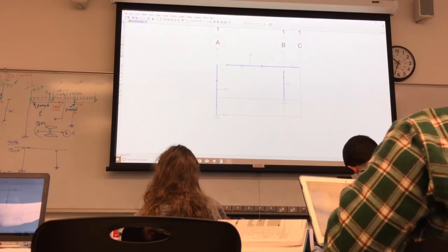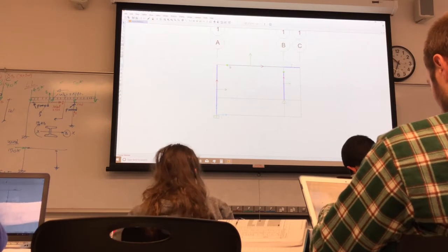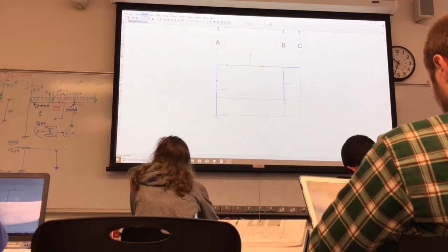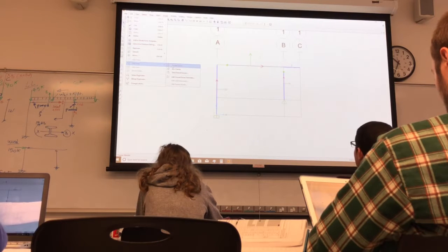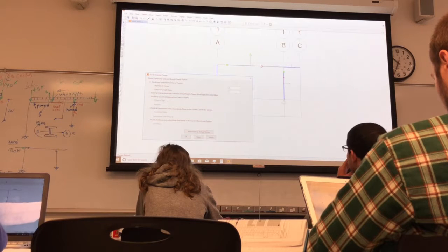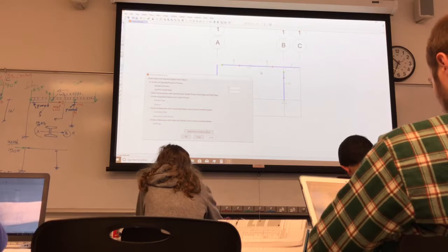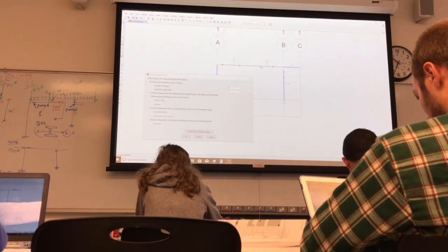The easiest way to do it is to select this beam and divide it into two beams. If you go to Edit, that's why we have the edit option, and then it says Edit Lines, and there's a Divide Frame option. Go to Divide Frame, it already gives you the number of frames. I need 2 frames, and the ratio is 1, so there are 2 equal frames. You click Apply, and it gives you a node in the middle. So that solves the problem. Now these are two separate beams.